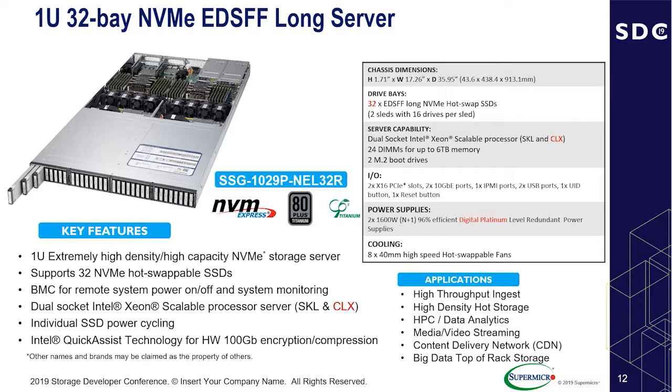It was great. The great reason why we could do that is because it really was just a connector change. We modified the connector that was on that backplane, or what we call a switchboard, from the Intel proprietary version to EDSFF, and it came up, it ran, and it's been awesome ever since. So we ran that for like 3 days straight at Flash Memory Summit. Everybody was looking at it thinking, great, it works. I'm sitting there going, wow, 3 days, that's really good, because we'd never powered this up before. So it was pretty awesome. I was pretty stoked. And we ran FIO, which is a nice little stress program, for 3 days, and it worked great.